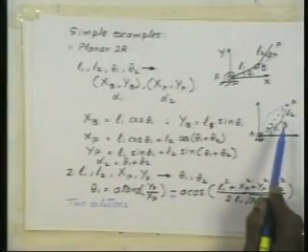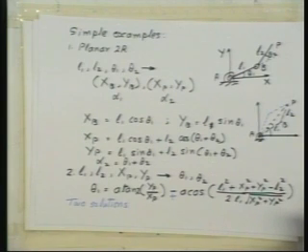So let me come to the 3R manipulator which you mentioned and pose this problem. Anything else to be determined here? Theta 1 has been determined. What about theta 2? That also has to be calculated. How do you do that? Yeah, we know alpha 2. No, do we know alpha 2 right now? We don't know. We have to calculate it. How do we get that? We know theta 1 now. We can find out where B is. Once we know where B is, we can find out the angle BP. That is alpha 2. Once we get alpha 2, subtract theta 1 from there, you get theta 2. That's clear? I didn't write it here.